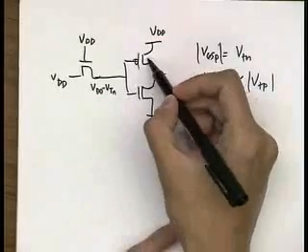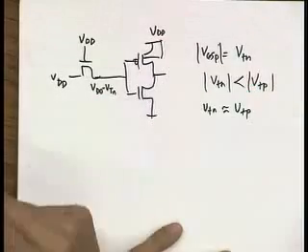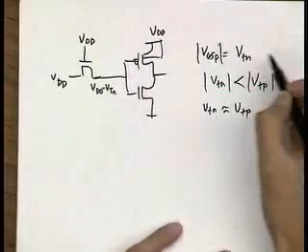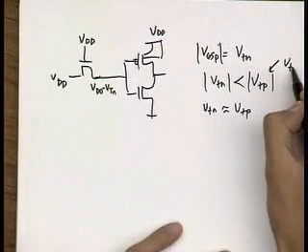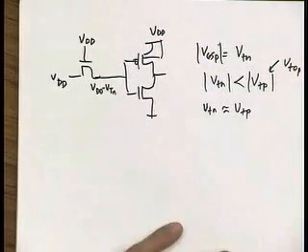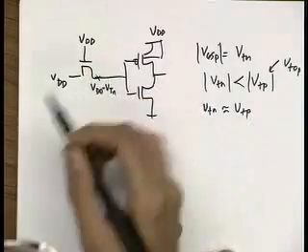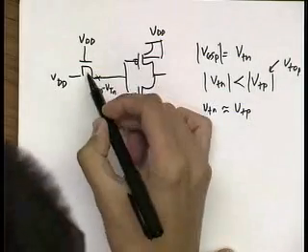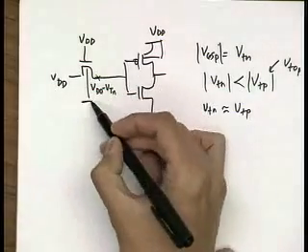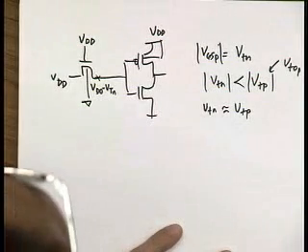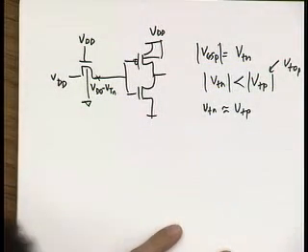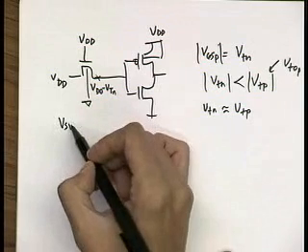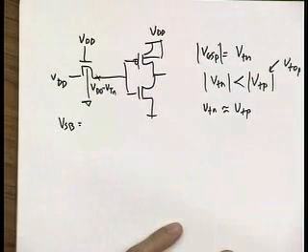Now, notice that here, the bulk here is normally connected to VDD, so the VT of the PMOS is just its VT0. Okay. What about for this transistor? Where's the bulk connected to? It's connected to ground, normally. So what's my source bulk voltage for this pass transistor?